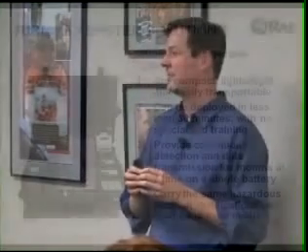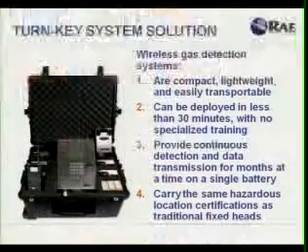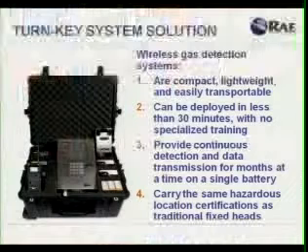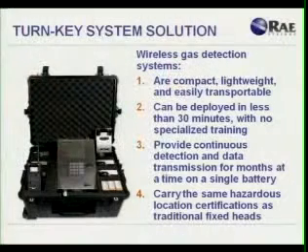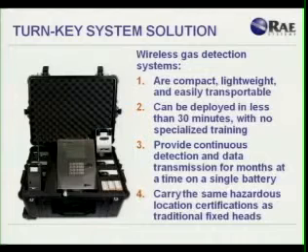And then again, as I just mentioned, with these wireless detectors there is no compromise when it comes to the safety aspect. All of our wireless gas detectors are certified Class 1, Division 1 for intrinsic safety here in North America. Internationally, we have ATEX and IECEx Zone 0 certification. So if you're moving from a traditional fixed head to a wireless system, there is no compromise on safety. You have the exact same certification levels for hazardous areas that you would on a fixed system.